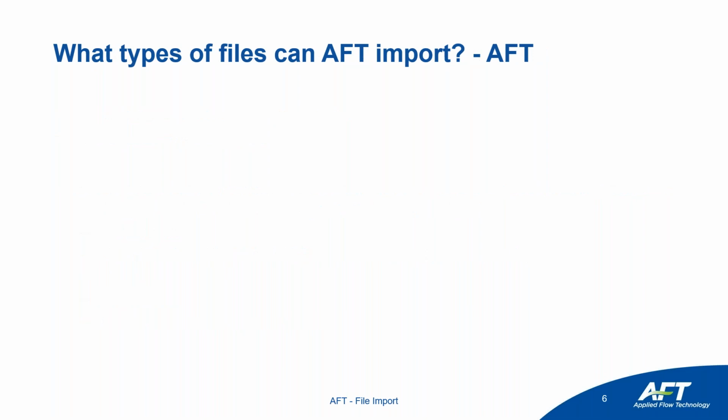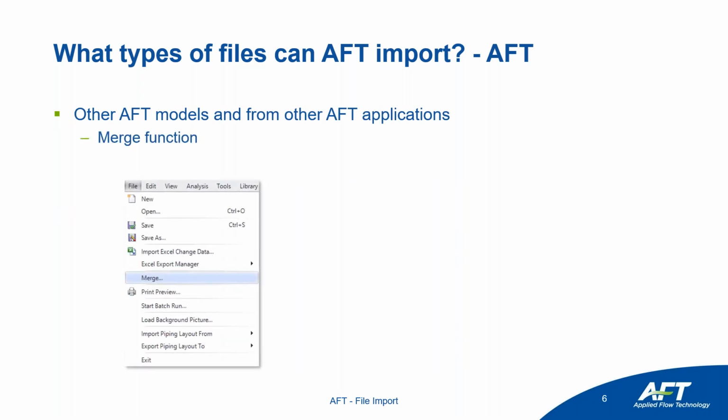So now we have a good understanding of why we would want to import a model into AFT software. So what types of models can AFT import? The first thing that we can import is other AFT models from other AFT applications as well. The first thing that we'll look at is called the merge function, which is found under the File menu, under Merge. What this does is it imports the selected file into your open file.